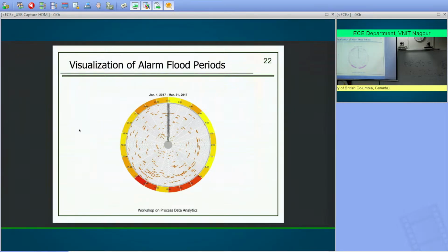So this is the inside of the lime kiln. Okay, so inside, when it's hot, when it's not hot. And these sections represent the sections that the infrared cameras are monitoring. So we took those images, stitched them all together in a way that allows operators to understand if there are rings growing inside the lime kiln, right? To get some intuition into that. And this was a very simple idea, but proved to be very effective in monitoring the system.